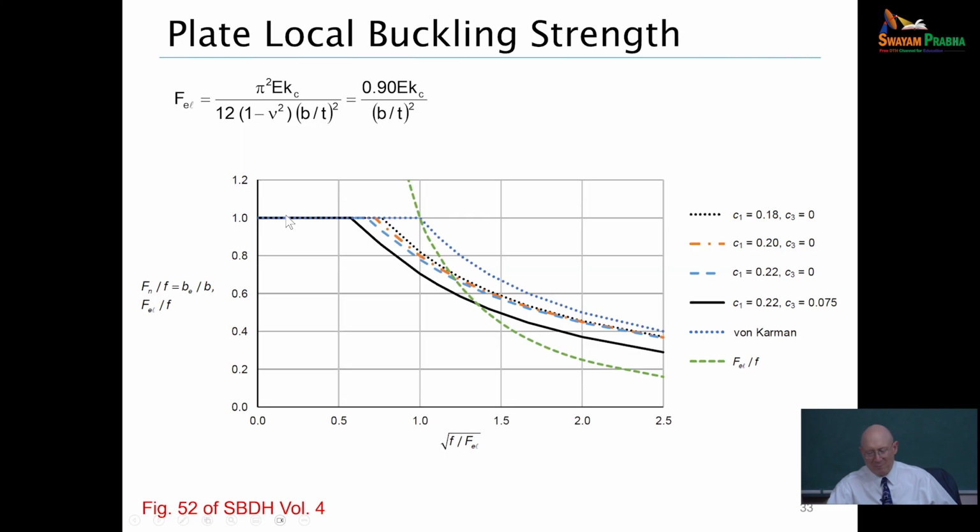So we would have a plateau strength there, and then you say, okay, we're going to count on some post-buckling strength. Now, we know that when we talk about plate buckling, you have supported longitudinal edges, and when the plate buckles out of plane, you develop membrane stress in the transverse direction. So that's quite helpful, and you can develop much higher stress than just the stress corresponding to initial buckling out of plane.